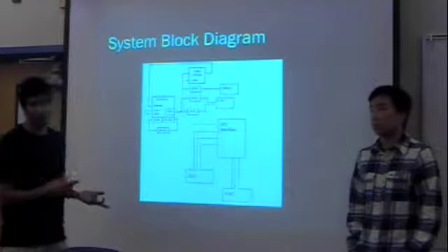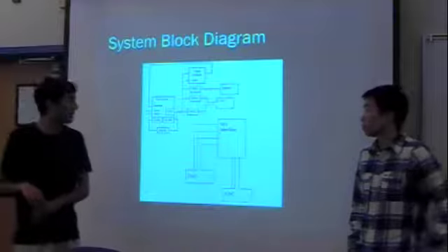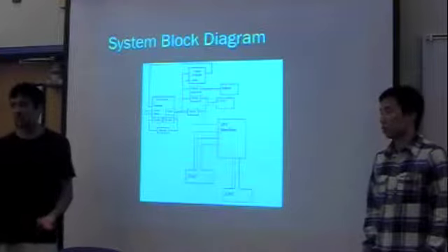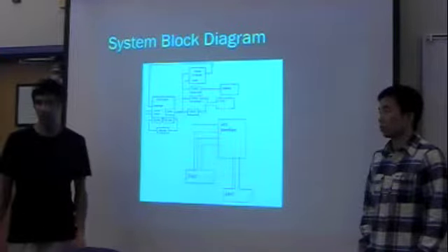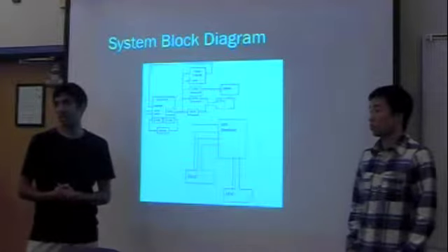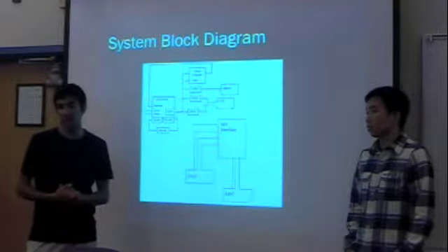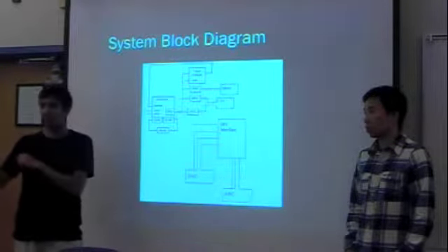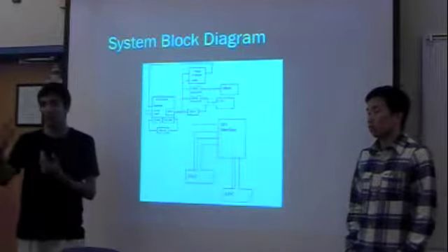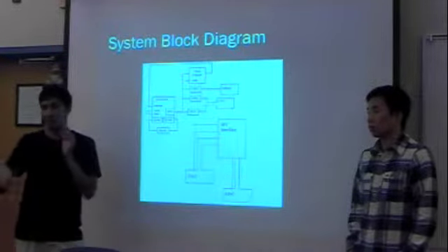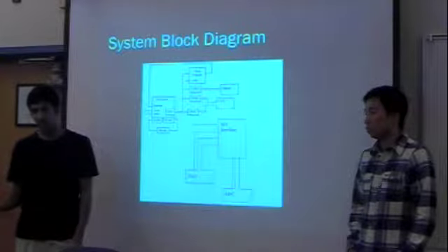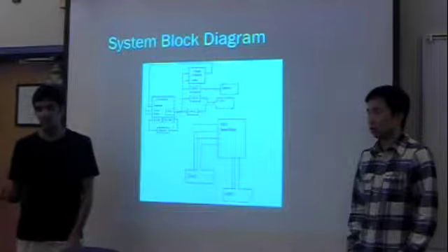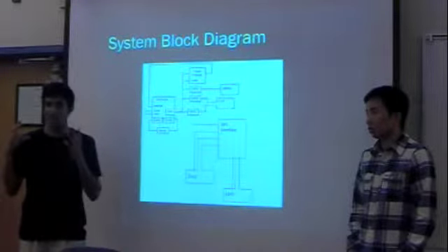So basically, like Aaron said earlier, we were supposed to have a filter in there. And because of the sampling constraints and the delays in C, we thought it'd be better to implement a filter in hardware. You can do that by using a user-defined IP core. You know how you drag IP cores into your system assembly view. You would actually have to write VHDL, import it in as a hardware core, look it up, and then synthesize it. So we wrote the VHDL for it, and when I turned on the speakers, it blew my ears out. I don't know what happened.